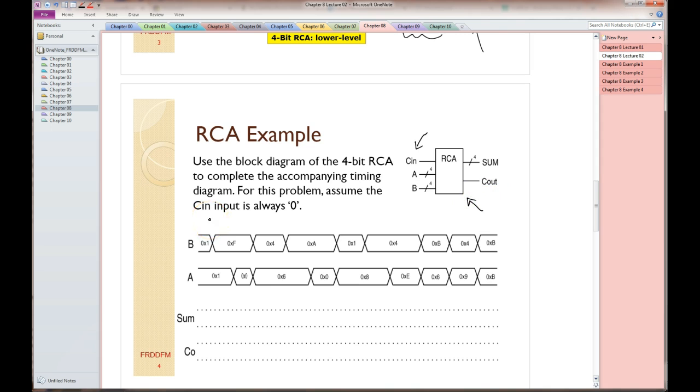Typically, for ripple carry adders, if I need a carry in, I put it there. If I don't need a carry in, I leave it out. This example happens to leave it in. So it's doing 4-bit math on this problem here. And so once again, I'm going to chop this up into sections so I don't make a mistake on this thing.